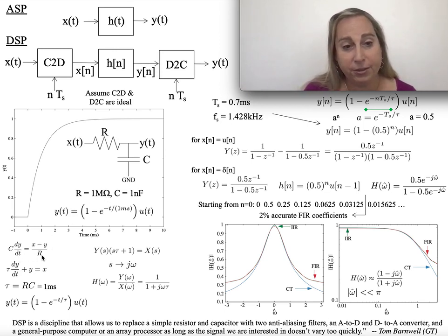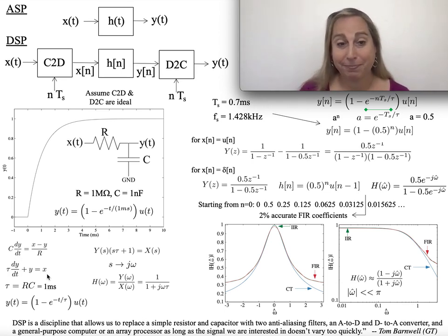And so you put this together, you realize there's an R and a C right here. You multiply through, you get a tau. That gives you dy/dt plus y equals x. This is about as canonical a first order system as you get. X is an input, an arbitrary input, so you might imagine there are things you can do with this.